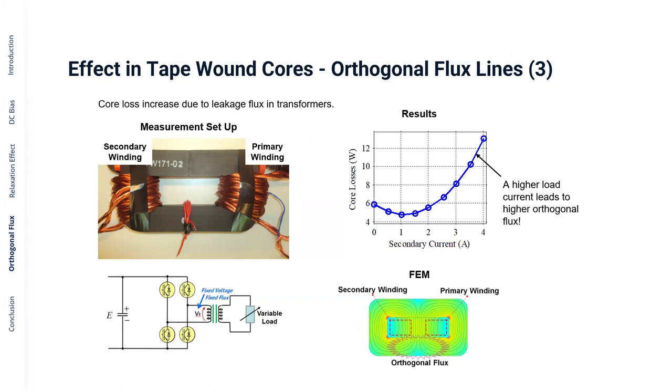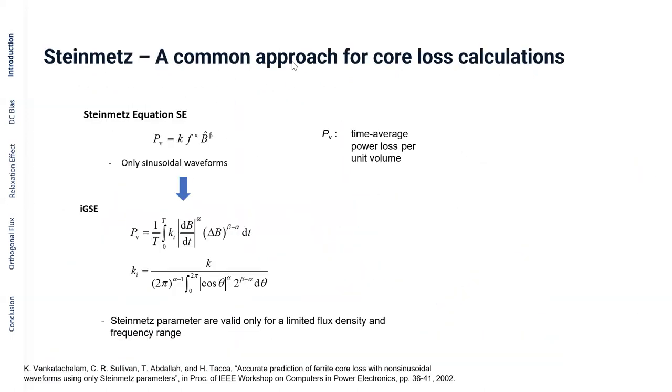Then the next question, talking about Steinmetz equations, are they valid in any operating condition? Yeah, high frequency. That's a very good question. This is a bit linked to this initial discussion I just had. It depends. You go to the data sheet, you take 3 operating points, and you get K, alpha, and beta. Now, if you get these 3 operating points, let's say at 1 kilohertz, your Steinmetz parameter will not be very accurate for 200 kilohertz, let's say. So you have to do this curve fitting in the operating range you're interested in.